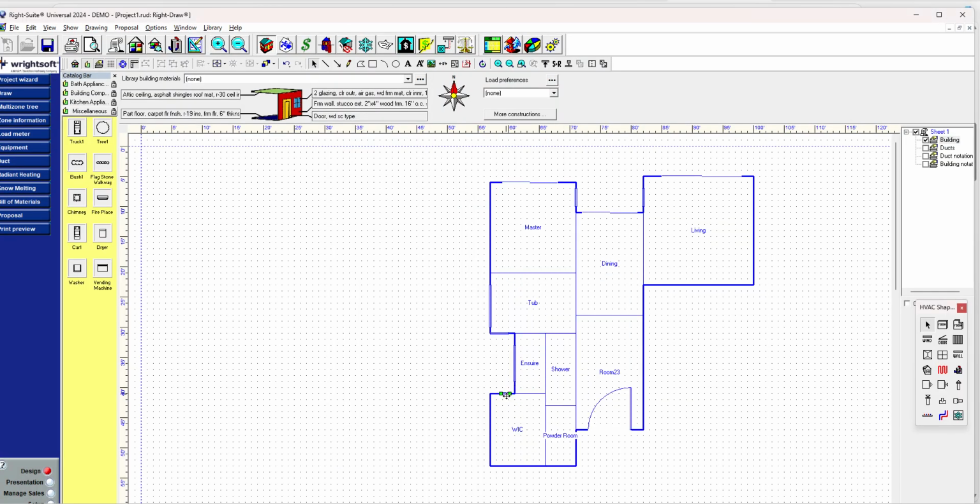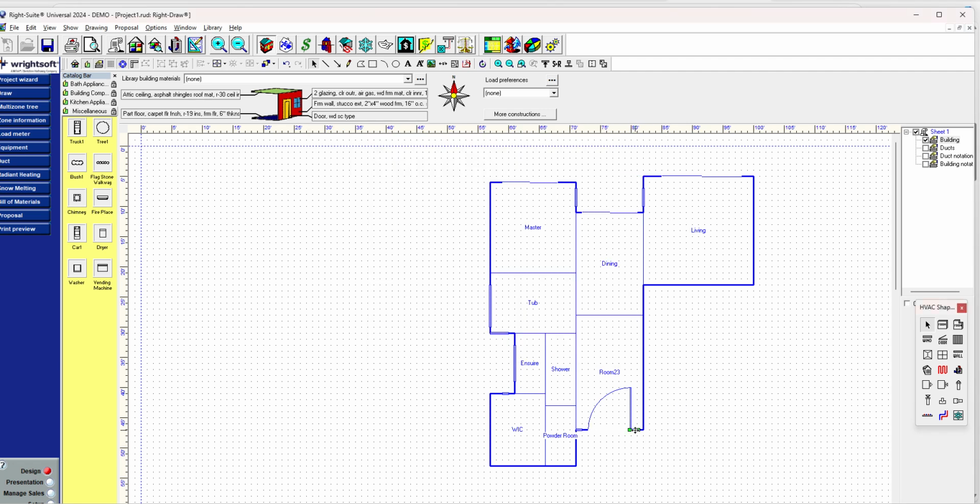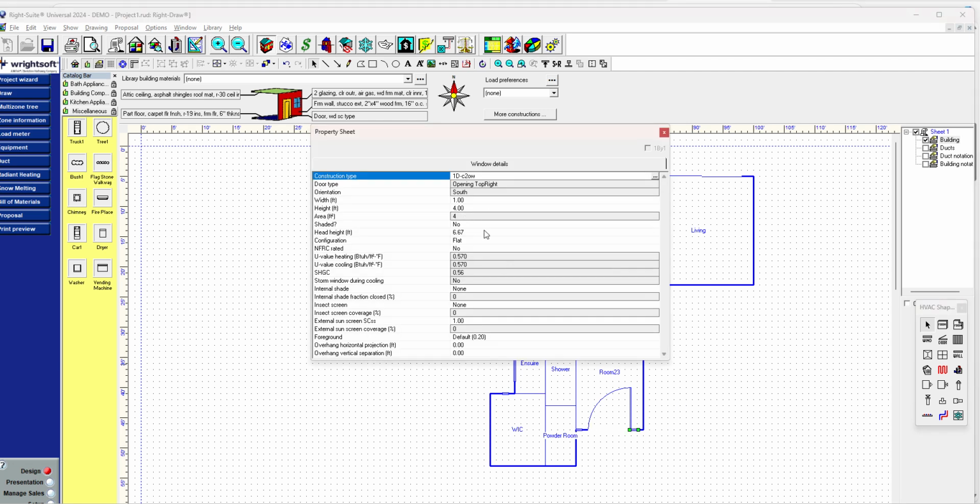We'll put in these small, tiny little windows, all right? And I know that these windows are going to be like tall and skinny type. So let's set these properties. These are probably like 8 foot tall. So that means 2 foot overhang. Good. And then this one, same thing. So it's like an 8 foot tall. No, oops. Head height is 2 feet. Height is 8 feet. Very good.